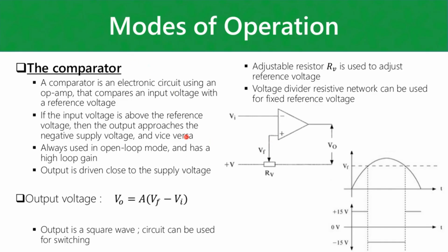All right, and then you also get the comparator. So what the comparator does is, if you just want to discriminate between two different inputs, or between an input and a reference, for instance, you have a sensor checking whether your water level is at a certain point, but you don't care what your water level is. You just want to know if it will drop below a certain value. So you either want a true or false answer. Right, so then you can use an op-amp comparator.